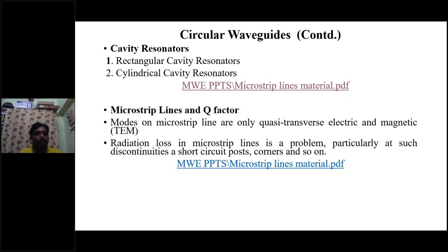But here, there is a possibility when we are transmitting in microstrip lines. We are using transverse electromagnetic waves. That's why we can extend this to microstrip lines, although it is not 100% propagation of transverse electromagnetic waves, but quasi, meaning only some part of the transverse electromagnetic waves is transmitted in microstrip lines. That's why in most cases, when designing our Wi-Fi and WLAN connections, we use microstrip patch antennas.